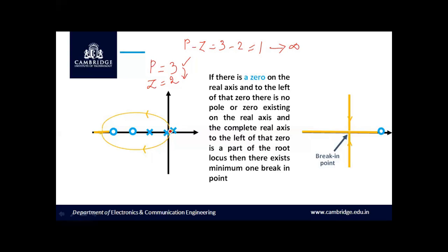So let us justify the statement. One of the poles at s equal to 0 with respect to increase in k will reach a point for a particular value of k in which we get a multiple pole, that is the breakaway point, and it breaks away, that is moving from real into the complex plane, and then here it breaks in and moves from complex plane into the real axis, and then it reaches open loop 0.